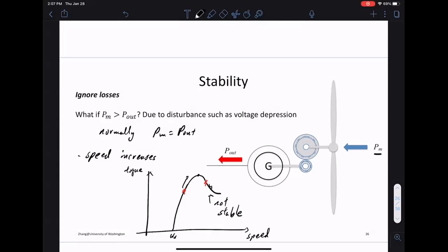What you're afraid of for type 1 is if you're operating very close to the maximum torque, the pull out torque. If you suddenly get more power from wind, there's no easy way to dump that power. Speeding up the blade only works up to a certain range because these are nonlinear characteristics. You cannot always dump power there. Then the interesting question is really, how do you get rid of power? And we don't always do it successfully.